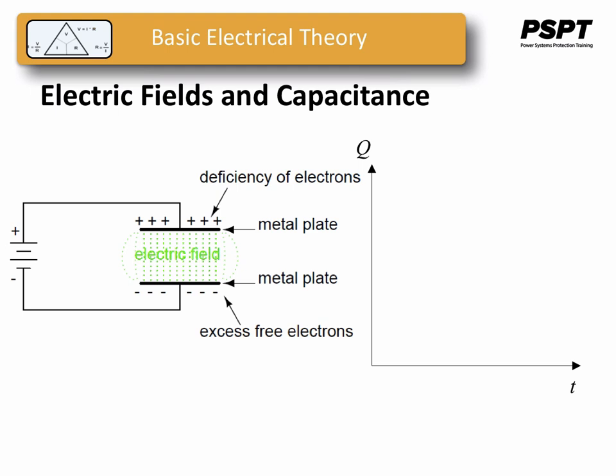A capacitor's ability to store energy as a function of voltage potential difference between the 2 leads results in a tendency to try to maintain the voltage at a constant level. In other words, capacitors tend to resist changes in voltage, whether it's a drop or an increase. When the voltage across a capacitor is increased or decreased, the capacitor resists the change by drawing current from the source, or supplying current to the source, in opposition to the change.